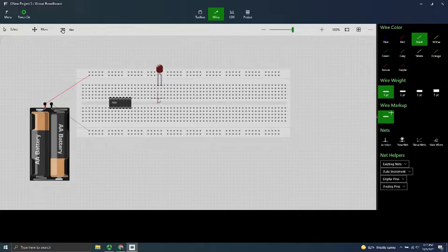And I'm going to use, hopefully I'm still in the right color, black, right there. Okay, I can do that. Oops, I didn't mean to do that. There you go. So remember, all of these are connected together. So it doesn't matter if I connect it to that point, that point, that point, that point. It's all one piece of wire underneath. So it's basically like connecting it to this pin of this LED up here.